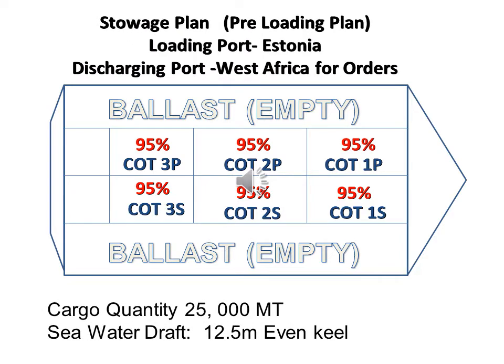Prior to loading, all cargo operations in a tanker vessel require utmost diligence in planning, and the most careful consideration will need to be made for a safe operation. The loading plan shall be posted in the cargo control room at a conspicuous location and distributed to all personnel directly involved in the operation. The loading plan should be signed to confirm the personnel have read and fully understood the plan.